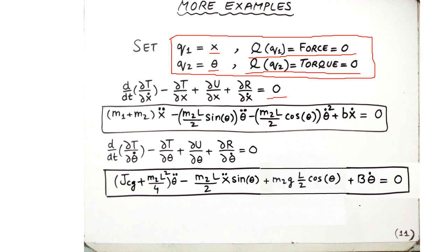Hence, on the right hand side of the Lagrange equation, there are going to be two of them, one based upon the derivatives of energy with respect to the velocity and the displacement of m1. The other Lagrange equation will be based upon the derivative of angular velocity of the pendulum bar, or its angular displacement theta. On the right hand side of both equations is 0.